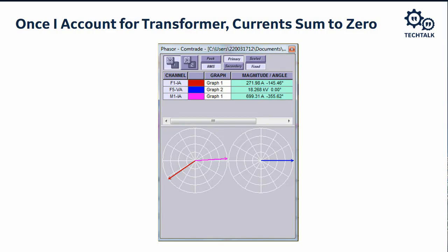Now, this particular relay is a G30. There's something unique about a G30 in that it can be a unit protection device. What that means is that inside of the generator differential, we can include a transformer, which is exactly what we've done here, which is why you're seeing the 30-degree phase shift on the red trace. Normally we expect the currents to be 180 degrees from each other on a generator stator. We don't see that here because it's got a transformer in there.